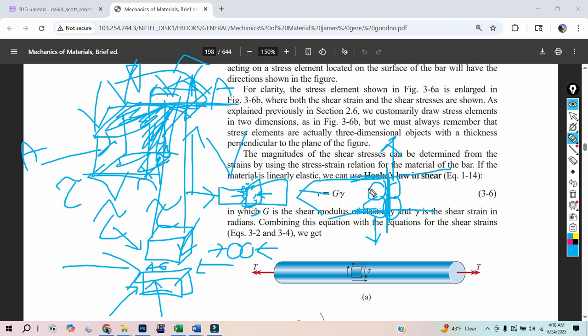But sideways pressure is that I'm putting a force right here, and that force is on that cross-sectional area. I still think it's kind of a made-up term for shear stress, which just makes it even worse. But what we're saying is if I'm applying a shear force, I'm relating it to the area that I'm applying that force. Because if I double the area, then the pressure reduces by half.